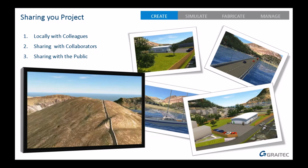Steve's asking about topography to Revit. No, sorry, it doesn't bring it in natively. There are things you can do. We can take the surface out of Infraworks, put it into Civil 3D, and then you can create an AutoCAD solid of that surface in Civil 3D and then link to that in Revit. That's option 1. Option 2, if you've got an earlier version of Revit, you can output the surface from Civil 3D as a LandXML, but they've removed that option in later versions.